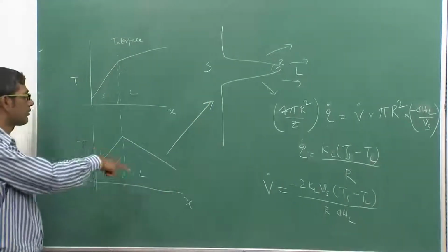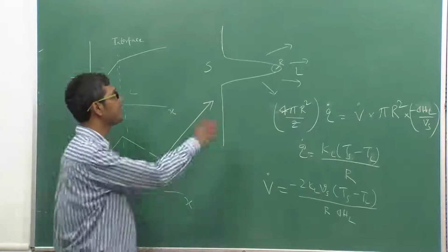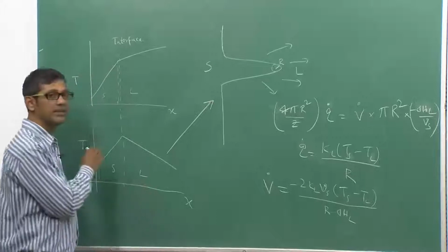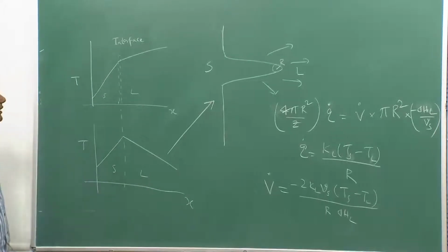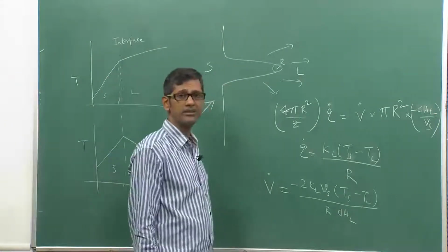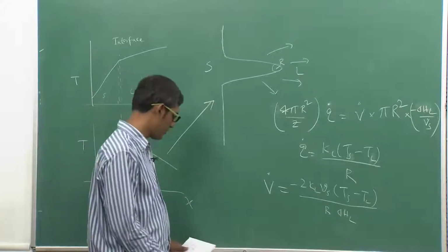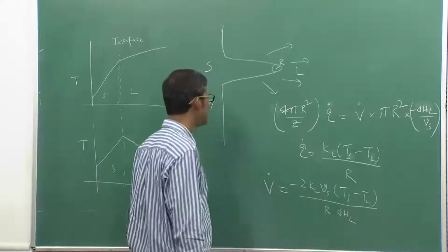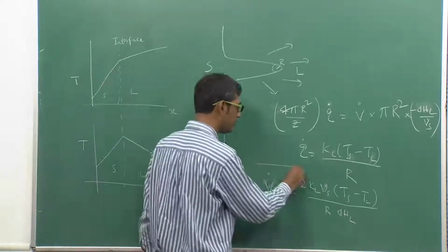So, liquid has a negative temperature gradient. So, heat will be basically rejected at the interface and transported to the liquid because of this negative temperature gradient that develops. Okay, heat can also be transported to the solid, but transport to the liquid is faster than to the solid, that is what happens. Okay. And so, this is the kind of calculation one can do.